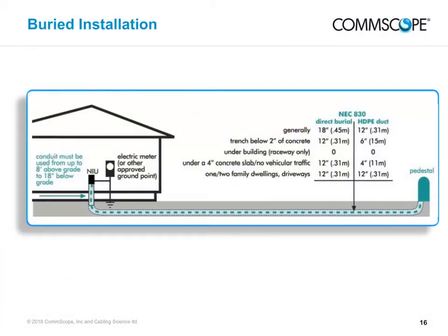Underground service has become popular in many developments and subdivisions. Broadband services are brought in by buried cable and accessed by pedestals, which are usually at the property line. While the easiest way to run the cable is to trench or plow in a burial-grade coaxial cable to a minimum depth of 12 inches or 0.3 meters, burying cable pre-installed in conduit is a far better method.